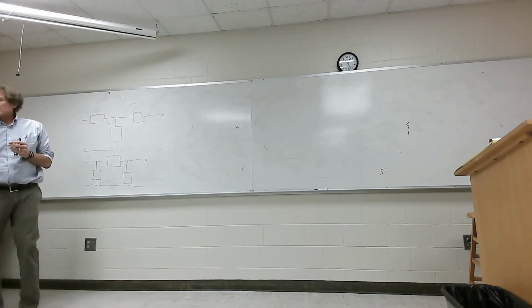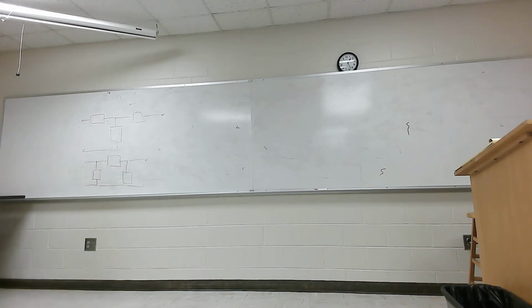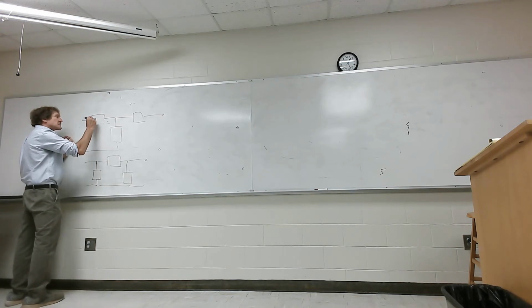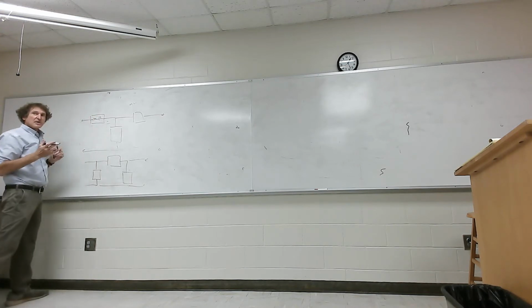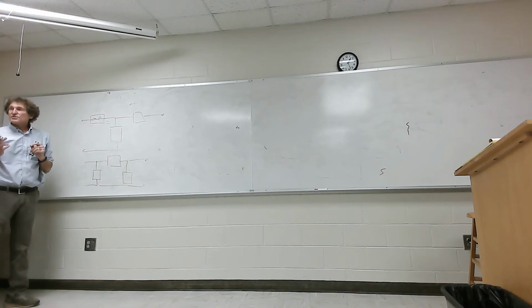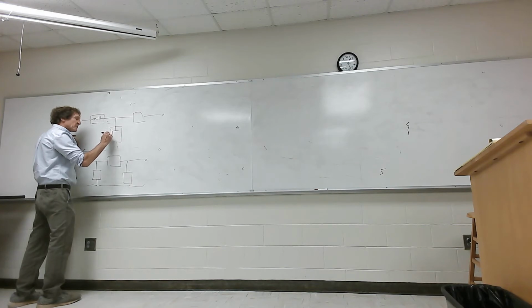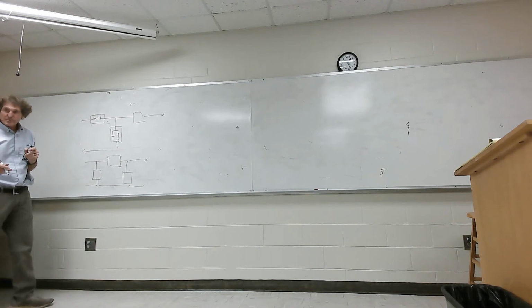When you have a band pass filter, you're passing over a narrow band of frequencies, and what you want here is a series LC circuit, because at resonance, an LC circuit looks like a short circuit. Y'all follow me? Here you want a parallel LC, because at resonance it looks like an open circuit. Everybody follow me on this?